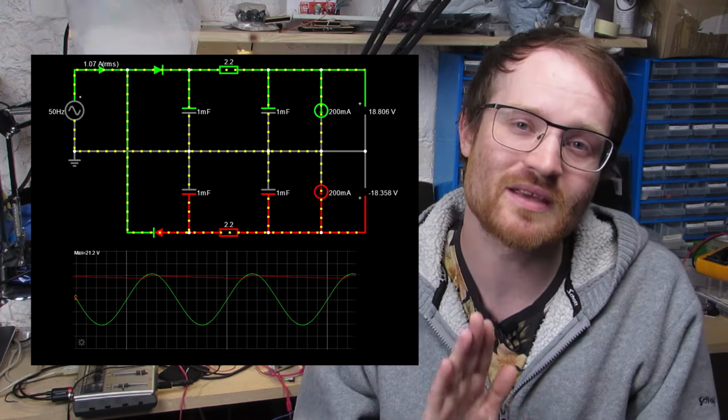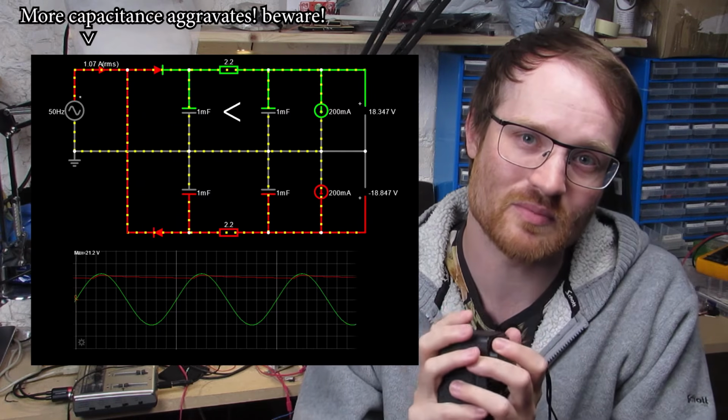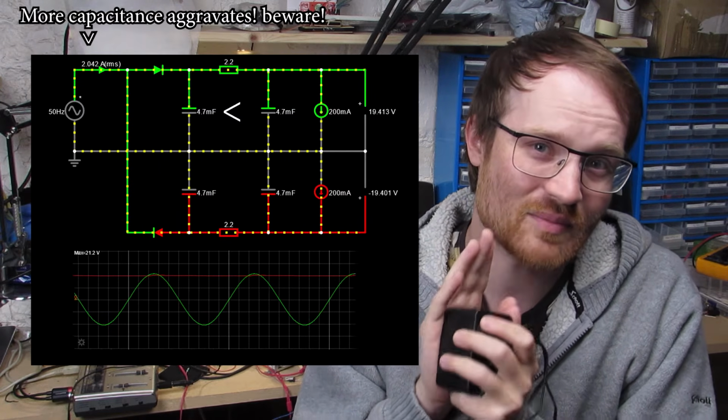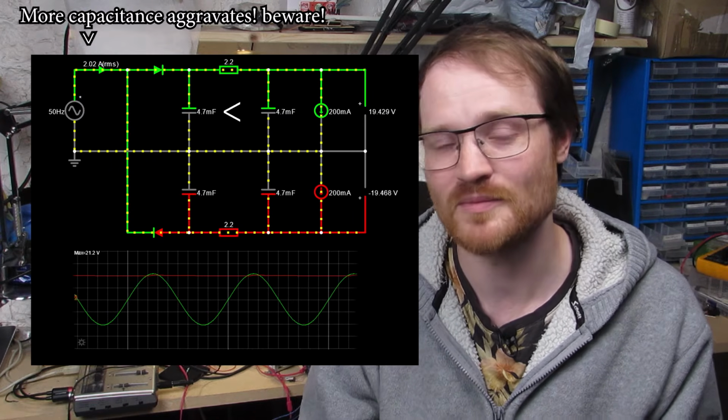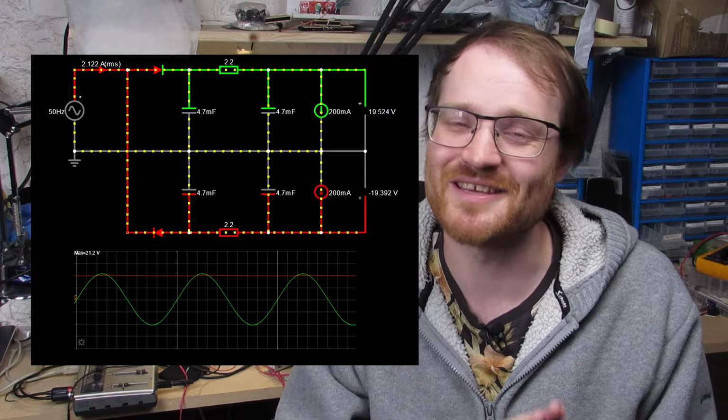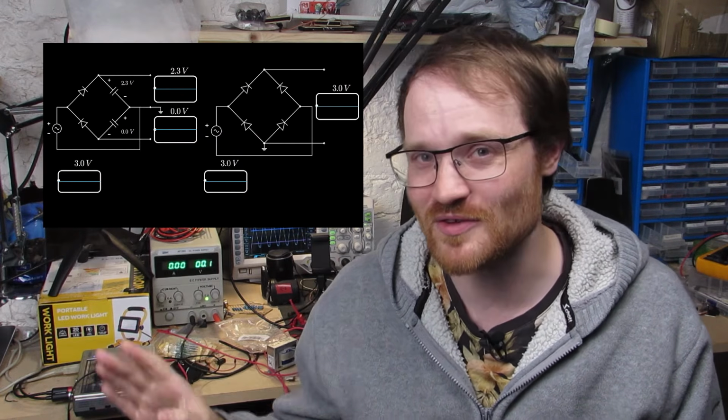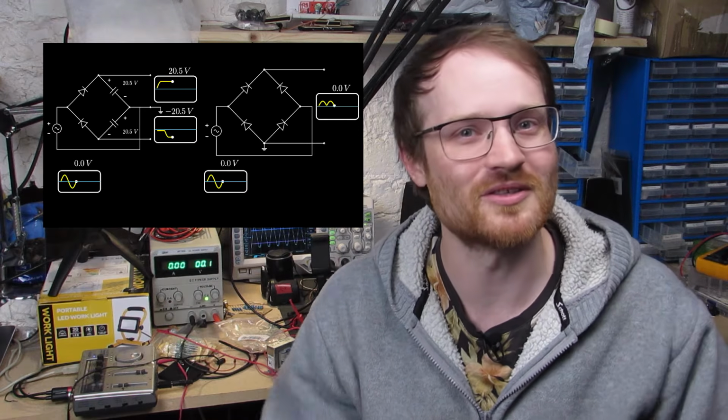This can cause your power supply to do funny things. Best case scenario, your transformer is going to heat up and fail early. Because we're making a simpler design that uses one of these power bricks, which don't have a center tap in their transformer, we can't do a proper full wave rectifier. Because of that simpler design, this is the drawback. There's always a trade-off in engineering. As I said, in a future video, we'll do a proper power supply design for a beefier power supply. So let's take that 200 milliamp figure and calculate the ripple voltage.